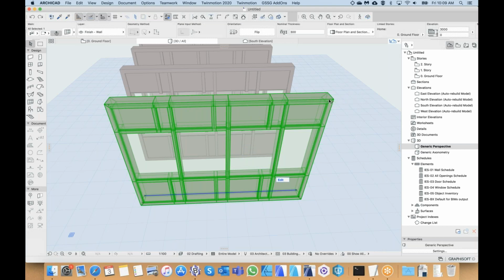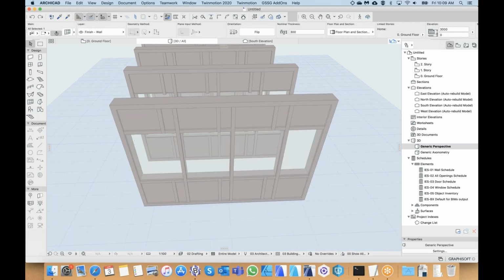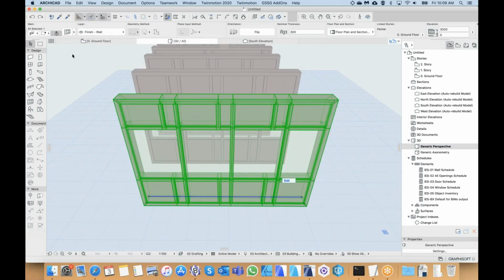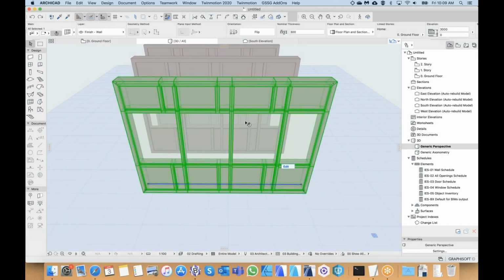Similar to a wall, we can grab the nodes on the top of it and stretch the height, things like this, and we can angle it. No problem. Okay. One benefit of the curtain wall is that it can actually be rotated in any XYZ coordinate. So it doesn't always have to be drawn as a line with an extrusion up. We can start curving it, rotating it.